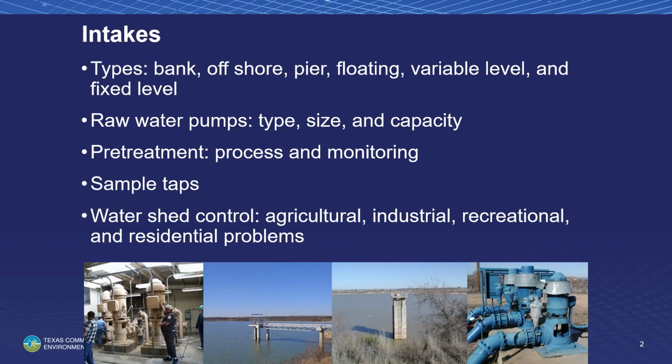There's all kinds of issues that you can find with intakes, particularly with the older surface water treatment plants. One of the big problems that I find, aside from some of the design issues that you can find in an intake as to where they put it and how long it's been there, is the fact that quite often we forget that we've got gates and wheels and valves and things on these that need to be exercised. As a result, your multi-level intake that's required of you quite often all of a sudden becomes an intake that only has one or two ports that are open.